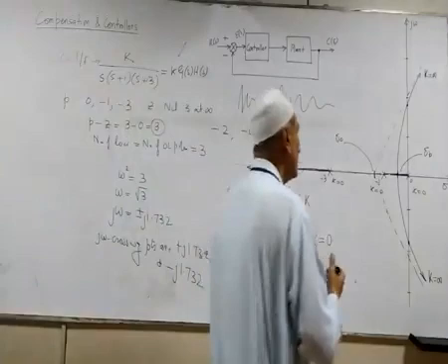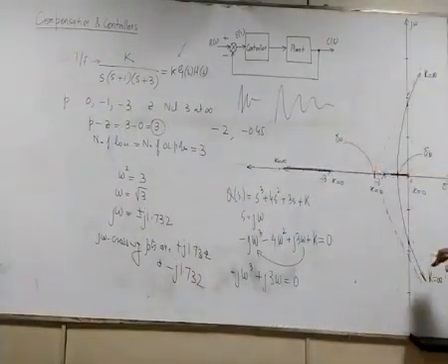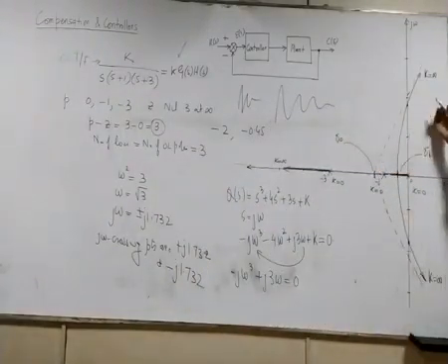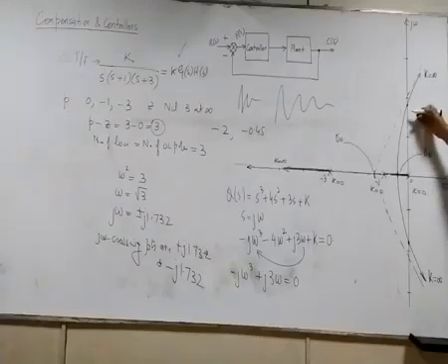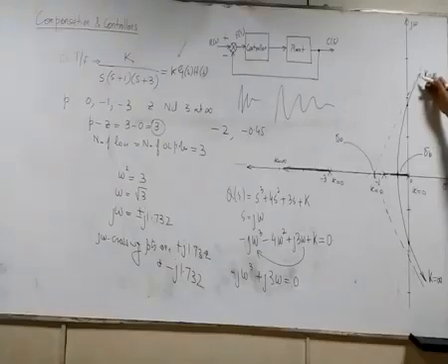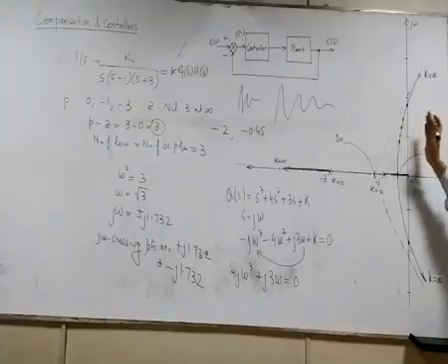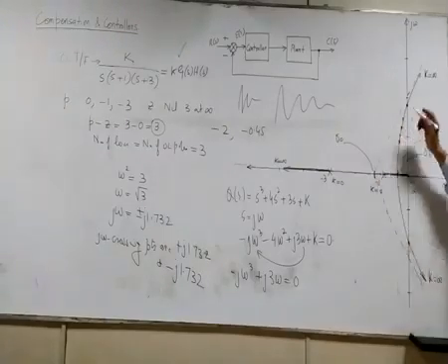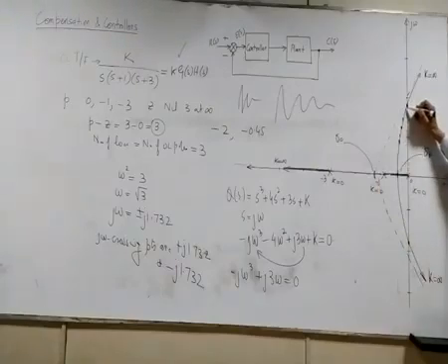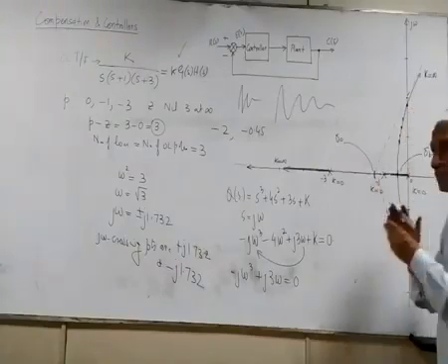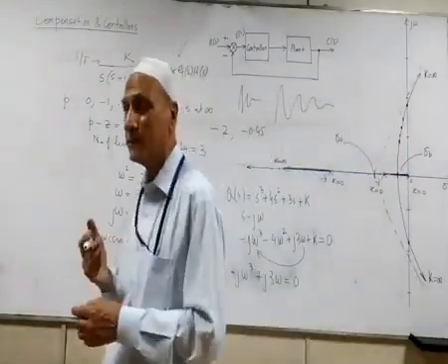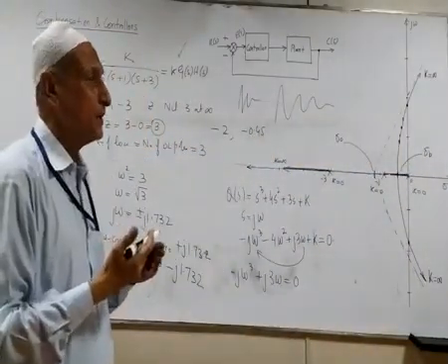And secondly, it is going into the unstable region after some time. For example, if you keep on increasing the gain, eventually the system is going towards instability. So this is the optimum point. Afterwards, the system becomes unstable, and you must work in choosing the operating point somewhere over here so that there is an adequate gain margin as well. Not right at the j omega axis, nor near the j omega axis. You must be a little further from the j omega axis towards the left.